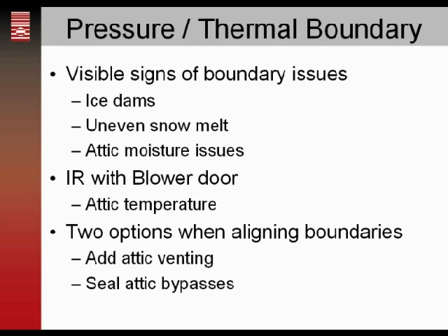And in cold climates, every once in a while we get 12 inches or more of insulation falling from the sky and accumulating on our roofs, and snow can actually be a pretty good insulator. So now that insulation was added to the roof overnight, our pressure boundary and thermal boundary are aligned, but they're not aligned in the right location. So the air is just bypassing the insulation on the ceiling, going up to the pressure boundary and the insulation on the roof, and warming up the attic spaces.